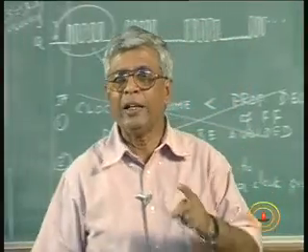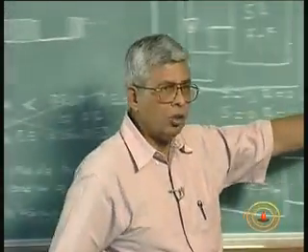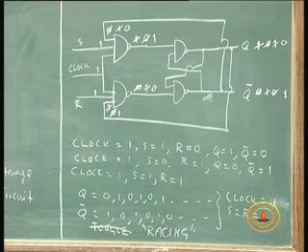In that case I have one extra feature over my SR flip flop. The SR flip flop will work as it is. There is no problem with other than the 1-1 condition, no problem. It is a good flip flop. It is not a bad flip flop, don't think it is a bad flip flop. It is a good flip flop. That means it has the 0-0 state. With clock 0, it behaves as a memory. With 0-0, it behaves like a memory.